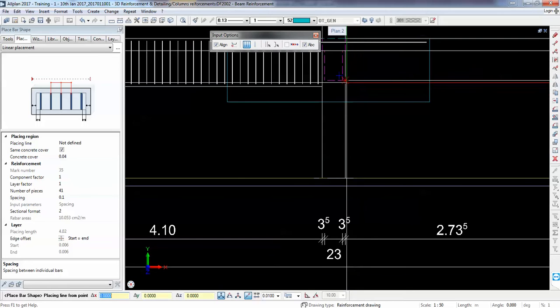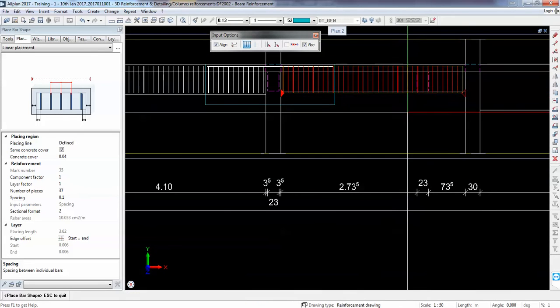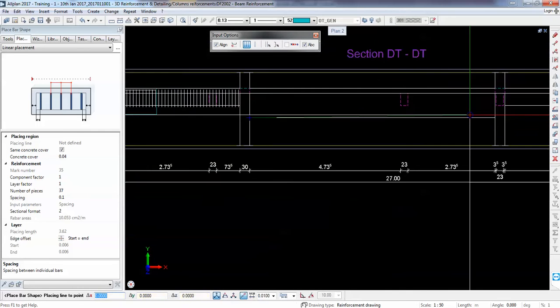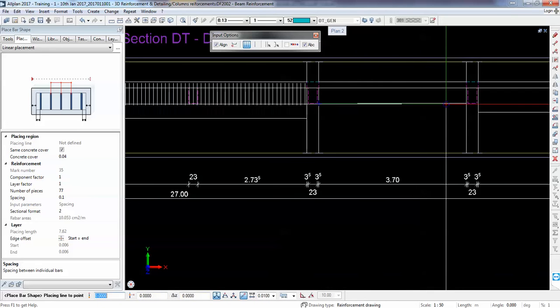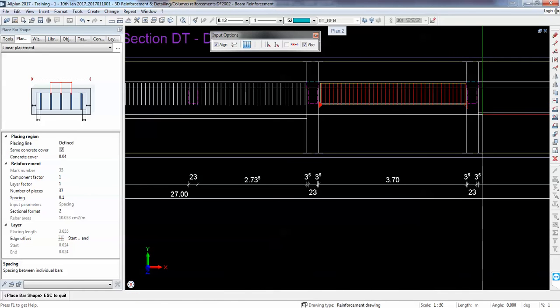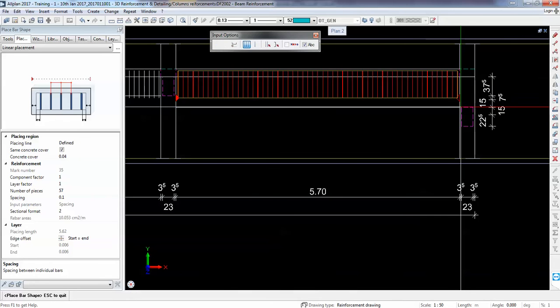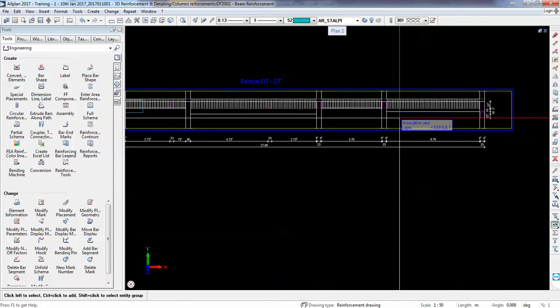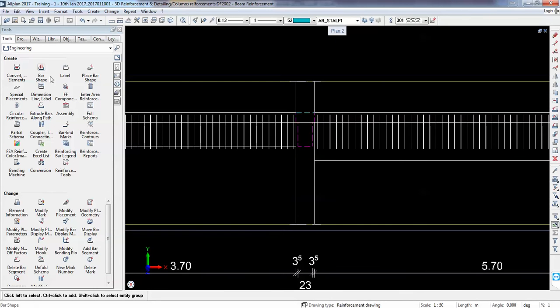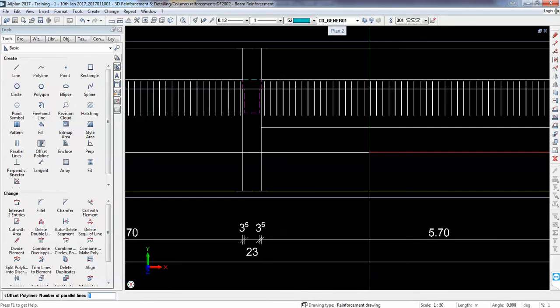Okay. I don't even care if the beam is shorter, or higher, and you'll see why. So you'll see how I work here. And I'll show you how fast I can adapt. Okay. Now, I would like to have the same stirrup, but it's impossible as some beams differ in height. What I'll do, I'm going to use the offset polyline as yesterday.